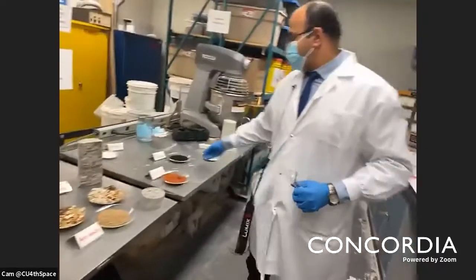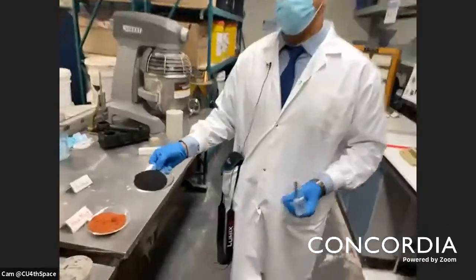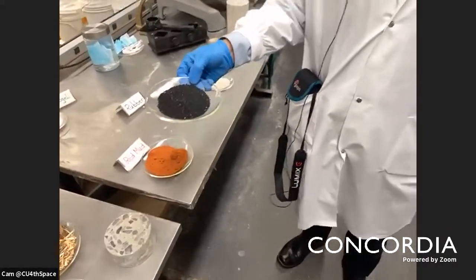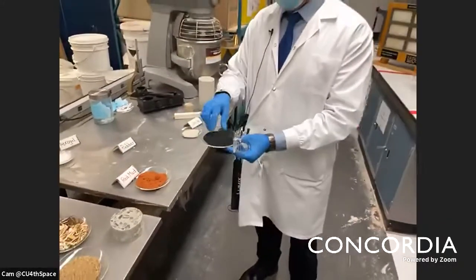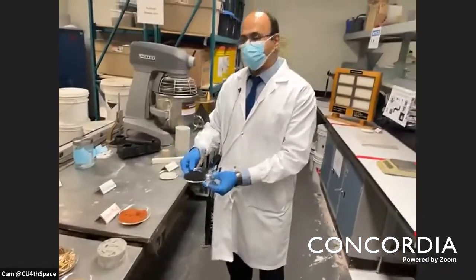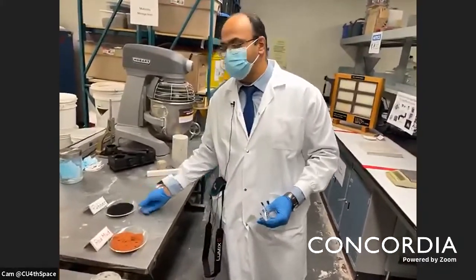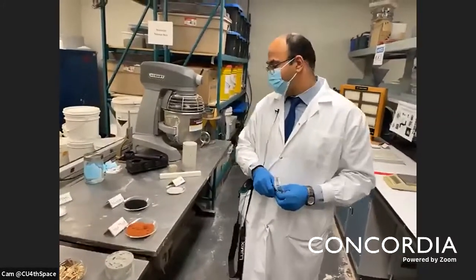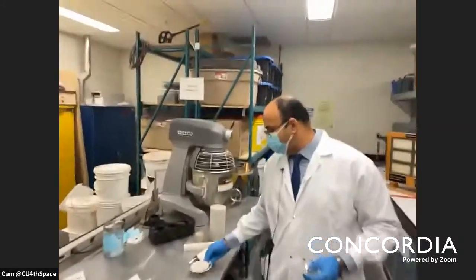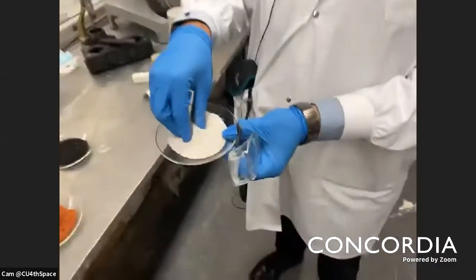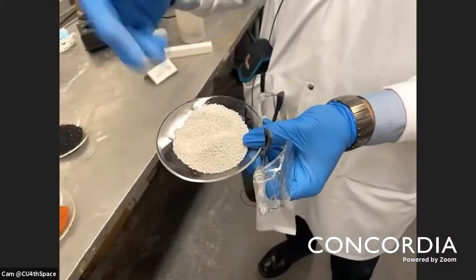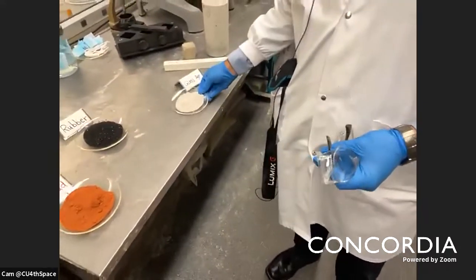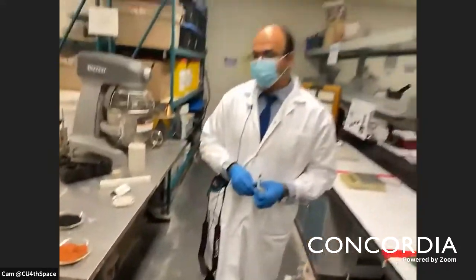Other than that, we can also have rubber. We can add it like this tire rubber, which is one of the main waste problems. We start cutting it small, and therefore we can insert it inside our concrete. And it's known that this will increase the impact resistance of our concrete. We have also here this very lightweight expanded glass, which we form from glass waste. And this will result in producing what we call lightweight concrete.